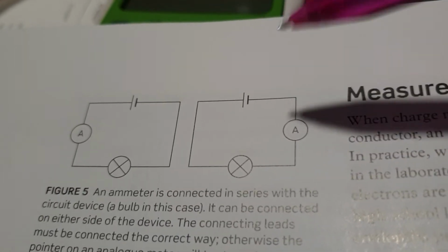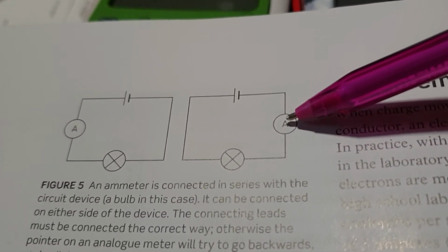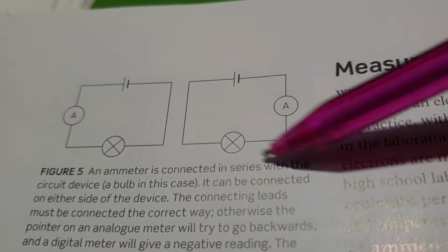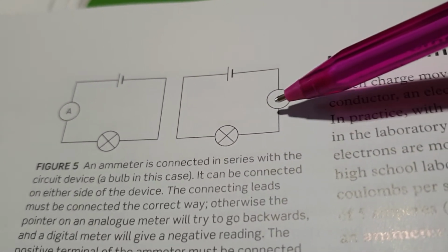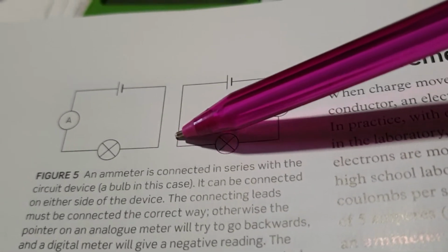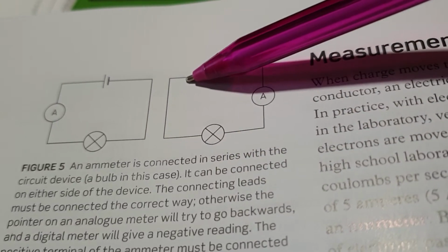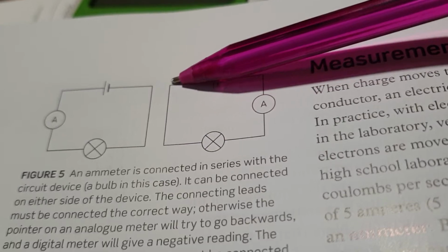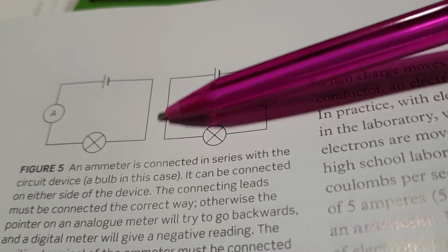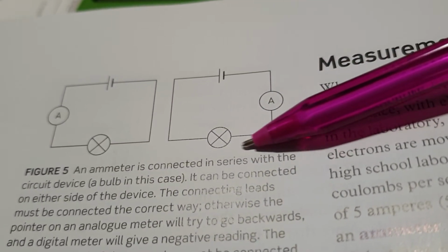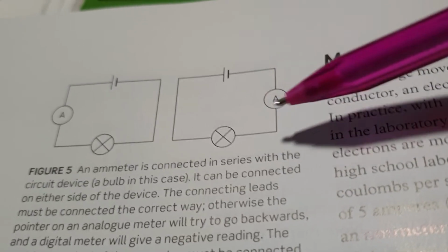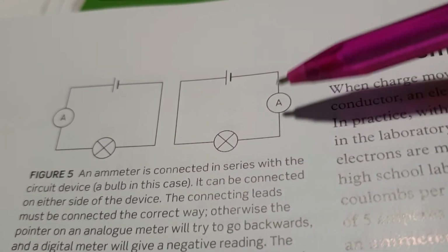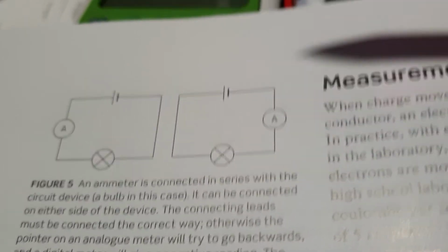All right. And then again, I'll just try and get a better angle. There we go. I mentioned before, the ammeter gets connected in series. It's measuring the current in this circuit, and it doesn't matter whether you put it here or put it here or put it there or there. The current is the same. The water flow is the same all the way, or the electricity flow, if you're thinking of that water pump situation before, it's the same all the way through. So it doesn't matter where in the circuit you place it.